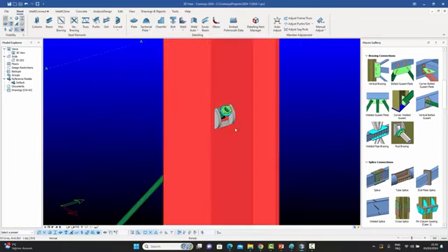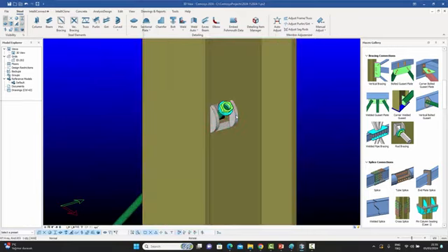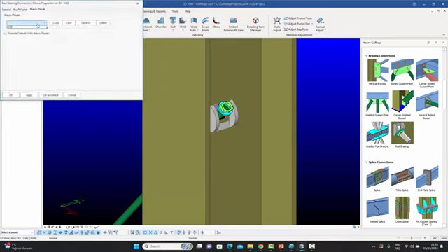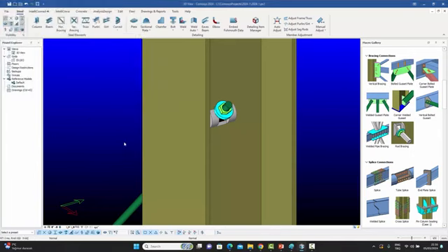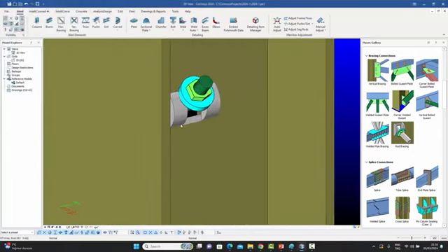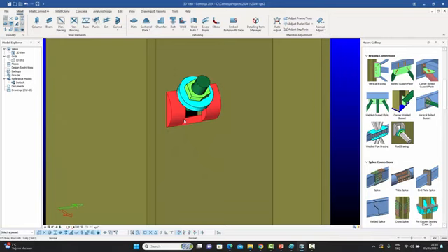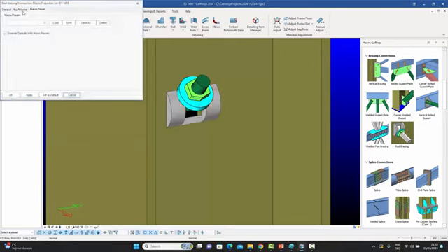I can zoom in and bring the standard company preset for this particular one. There you go. And basically, as you can see, it places this standard off-the-shelf piece. It's called a hillside washer at that point, and allows the rod to just run through the column. And with the big washer behind it, it allows you to tighten it from the backside. And inside you have details.